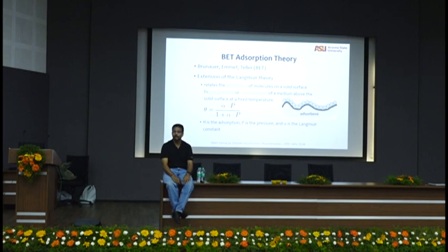So, how will you do it? You can say, oh, I'll take it out, spread it out, and then measure it. Can we do that for cement? This is in space, so I have to squeeze something in that is smaller than the layers, and then find a way to spread one molecule of what I am pushing in onto the surface of all of those. Once I'm sure all these layers are covered with one molecule each, I can find out how many molecules I have sent in, and therefore I can find the surface area. See how complicated it is?